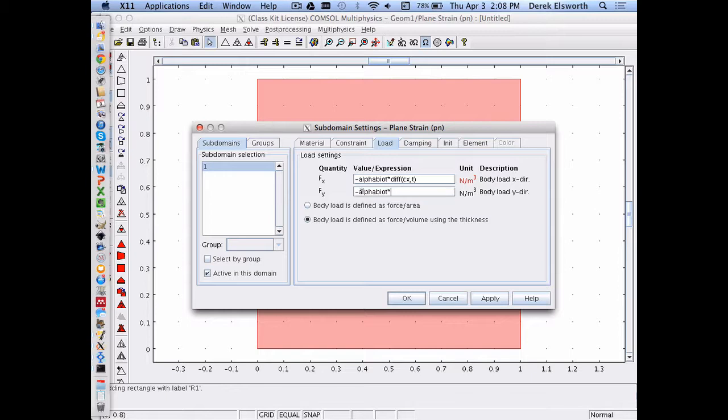I mean, we can make sure internally that our units are the same. COMSOL is a little different in that it's set up to have actual units that you apply, but with most finite element software, so long as you use consistent units, you're okay. You can check whether the units are consistent. And I guess we could check whether the units are consistent in this particular case as well, right?